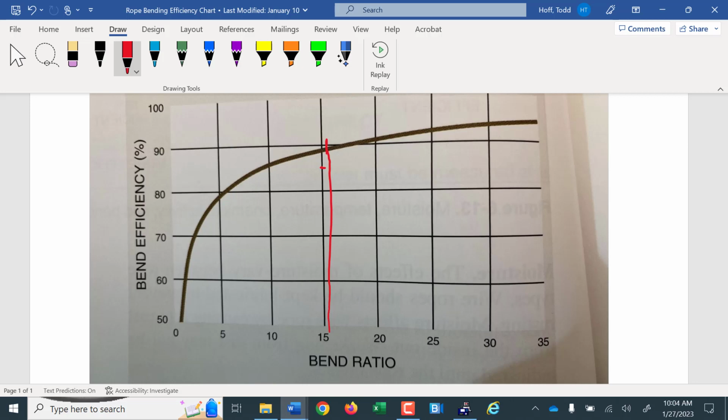We're going to have safety margins in this anyway. That's one of the things we'll talk about. Any sort of overhead lifting, you have huge safety margins. I mean, like you reduce the expected strength of it by dividing by 4 or 5 at least. So if we round it up to 90%, it would probably be okay. I'm going to call this for now 89%.